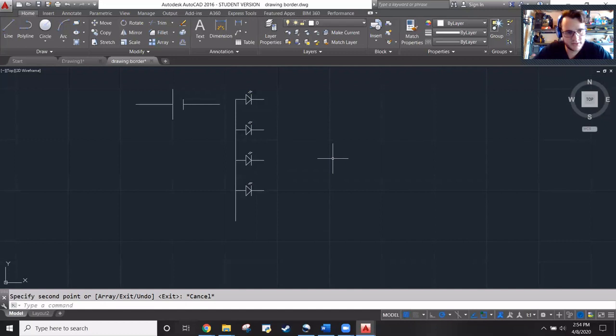To be honest, I really hate drawing with grid snap on. It's kind of a pain in the behind. So a lot of times what I'll do is I'll do some spatial layouts of reference lines with grid snap on, just to get my grid going, and then I'll turn it off and do all the rest of my drawings based on these reference lines. It's kind of a preference thing. You can play around with it, figure out what you do and don't like, but just be aware those options are available to you.